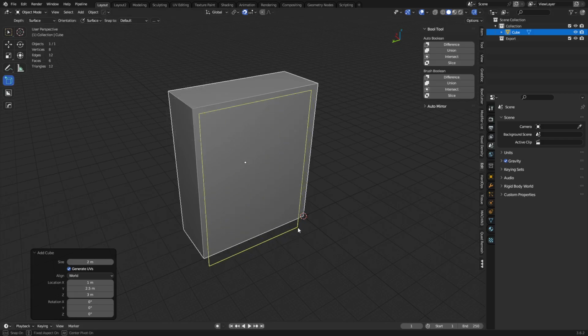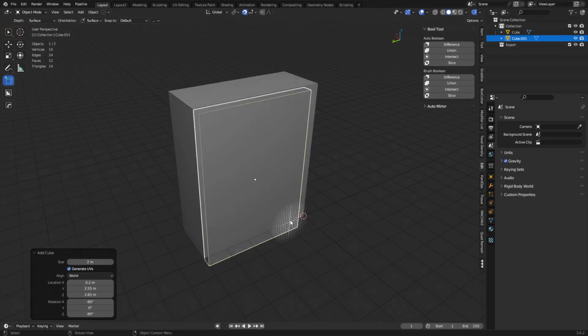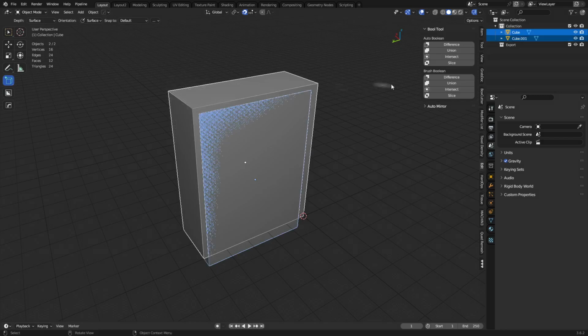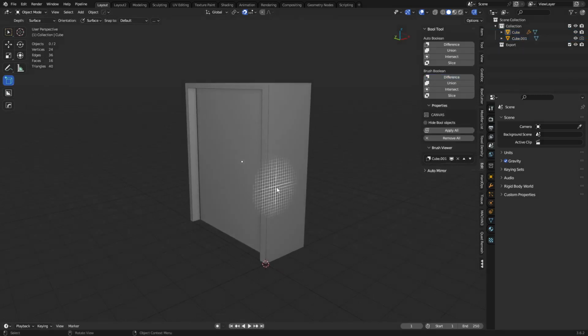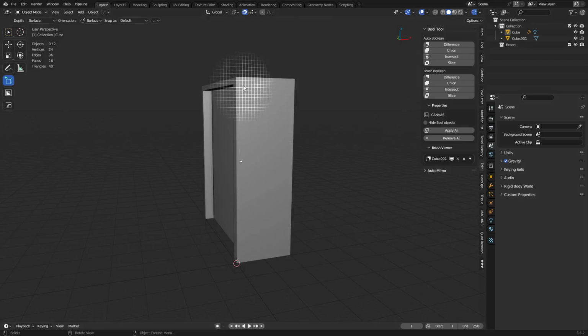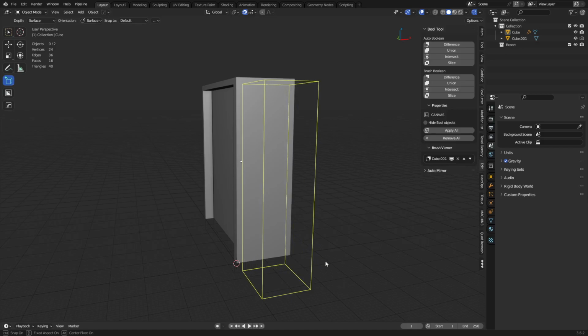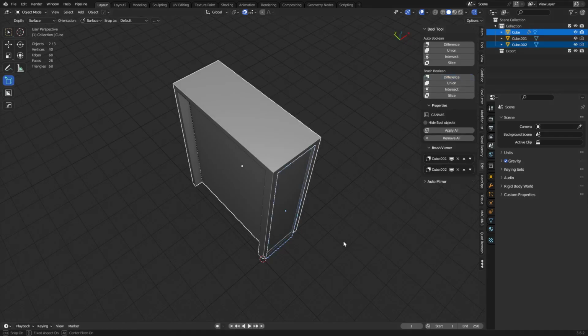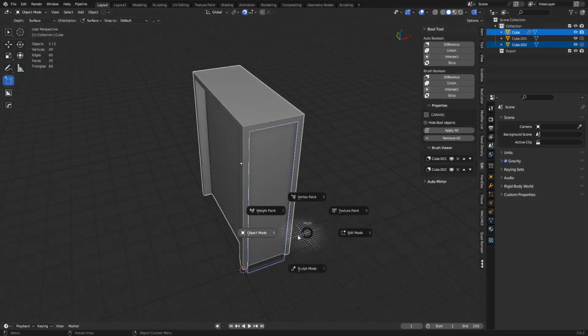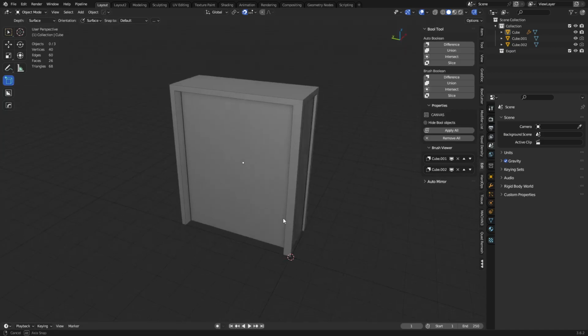But we can easily do a shape like this. And then, once we create it, it selects it. So Shift click the main shape, brush boolean difference. We can start using it, something like Box Cutter. So this is actually quite useful. Now, of course, Box Cutter has other features that you won't have available doing this method, but still quite useful as a workaround, right? So you can have fun with that one if you want to.